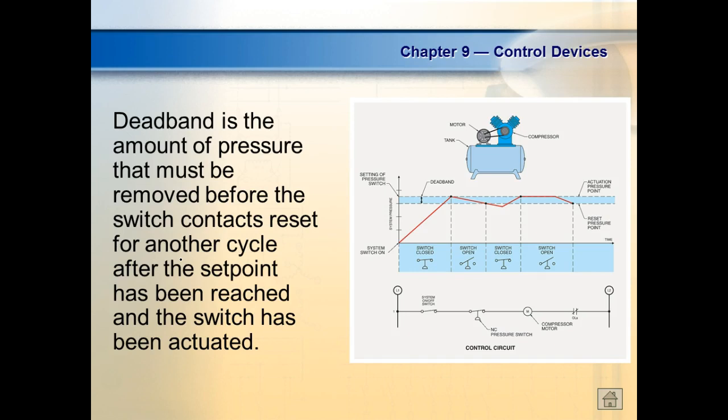Most of the motors that run are not continuous duty motors. They're what we call intermittent duty motors, because they're designed to cut on and cut off. So if you got a compressor whose motor runs all the time, odds are you need a bigger compressor, or eventually you're going to burn your motor up. So that's what I just showed y'all.